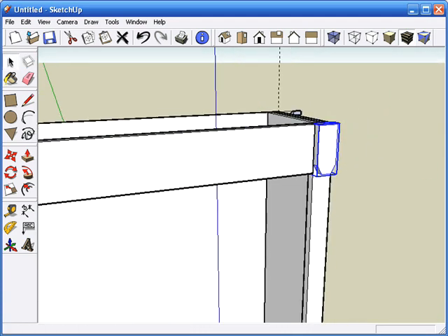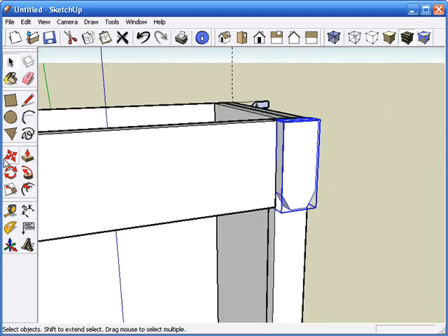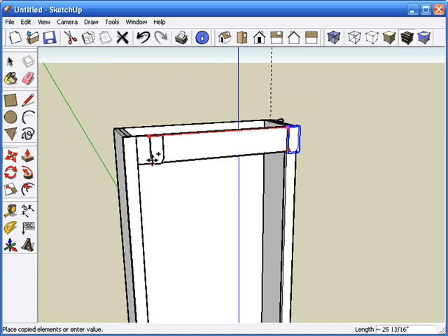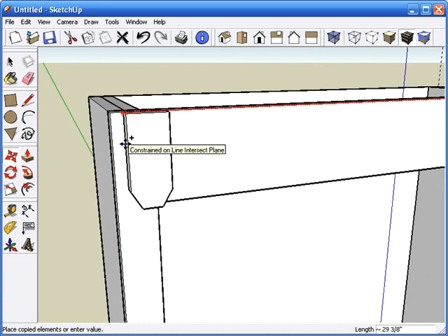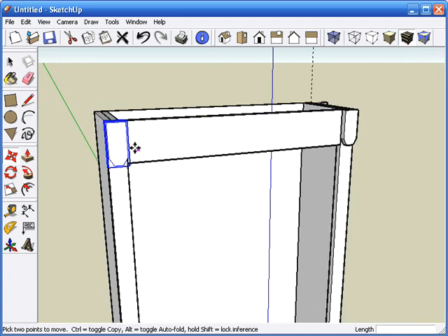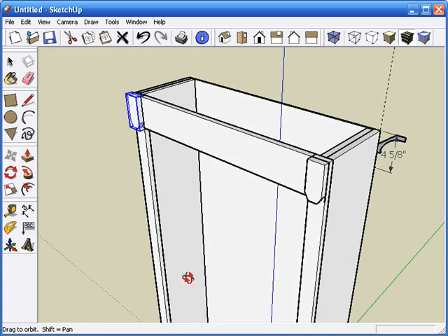Now let's take that component, and you notice I'm doing the same thing. Use the move tool, hold it from the corner you want to move it from, the corner you're going to want to use to stick it. And this is the corner I want to use to stick it. So I'll hold down the control key, click the left mouse button, and pull out my copy. I'll hold down the shift key to lock in the axis so it won't go all over the place. It'll only slide in that axis, and I'll stick it with that corner right to the edge of that other style. And that's what I meant by pick the corner you want to use to stick it. So think ahead. So there's our pieces, our 2 end blocks.